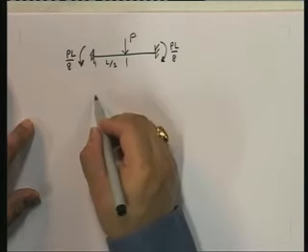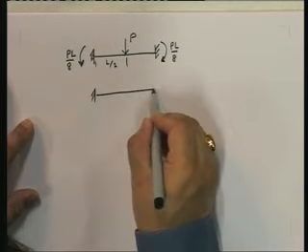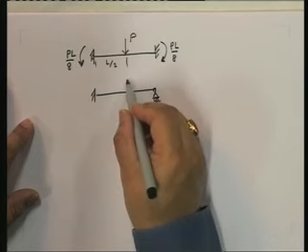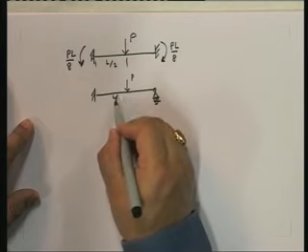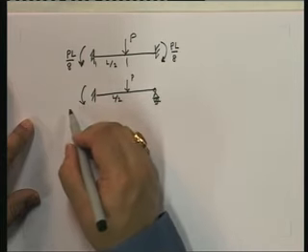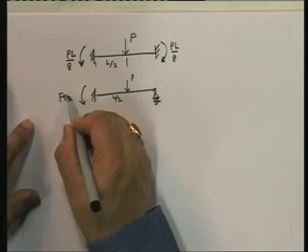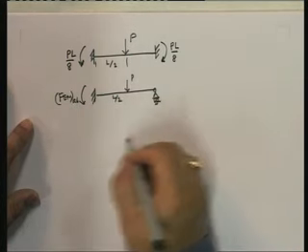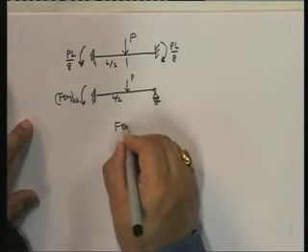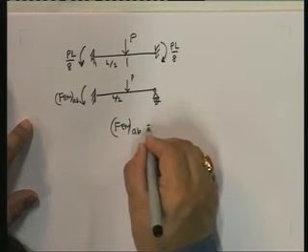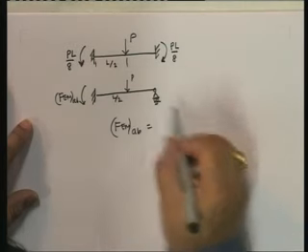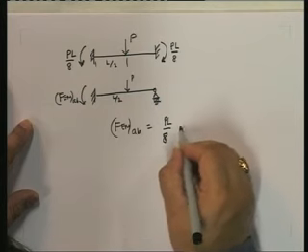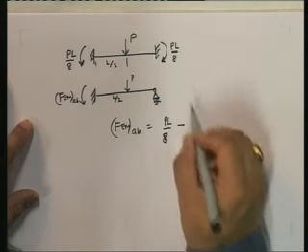So if I were to find out, for this situation, load applied at the center, what is this fixed end moment equal to for the modified beam? It is equal to PL by 8, because fixed end moment at AB, minus fixed end moment at BA.